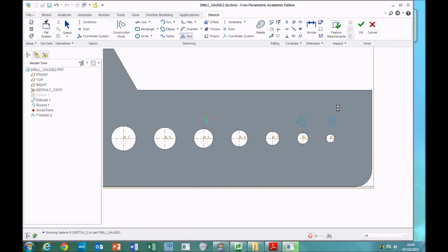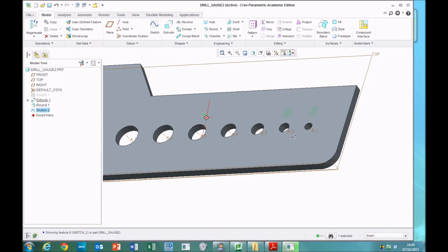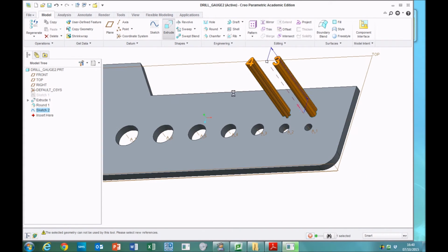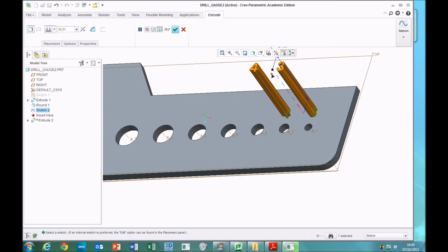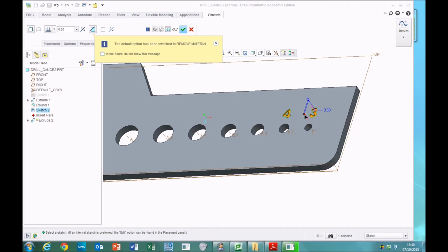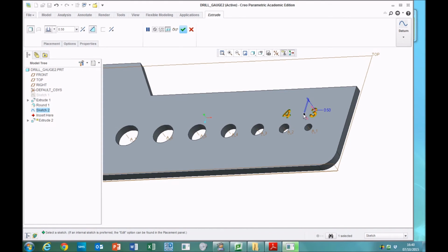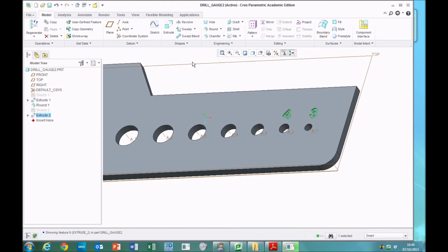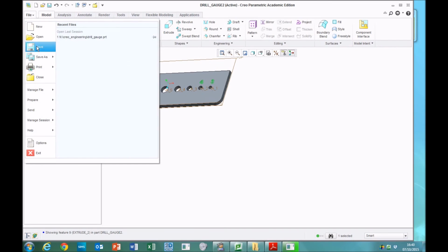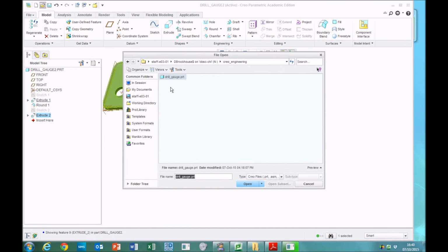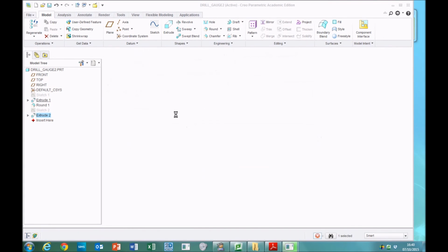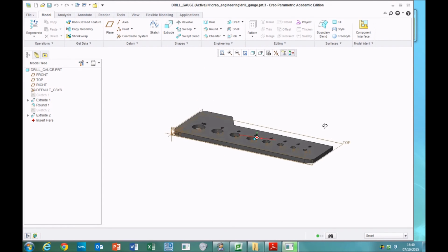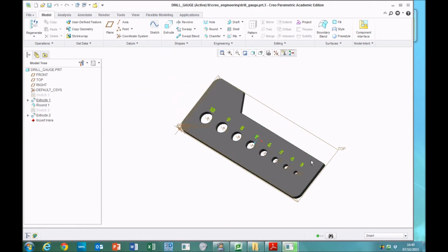And when you're finished, you click OK, and then go to Extrude. And obviously, instead of having it extruding outwards, we're going to push that down using the yellow box, push it back down, and we want it to go back in by 0.5 of a millimeter. So it's as if it's been embossed in. And then click OK. When it's finished, it should look a little like this, alright, with all your numbers on it.